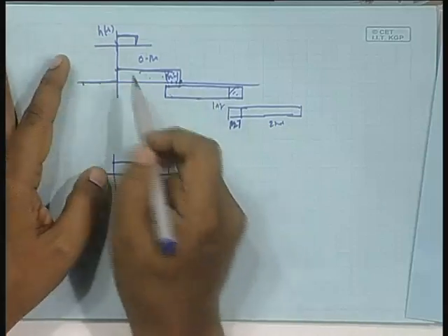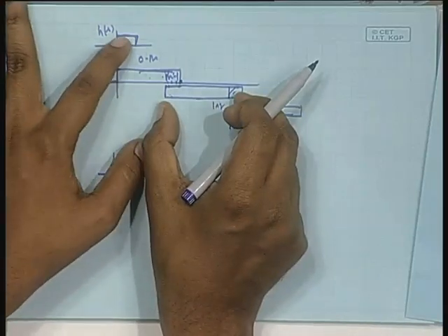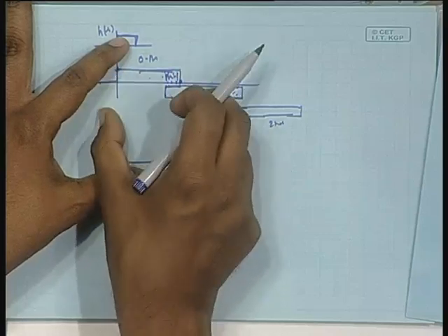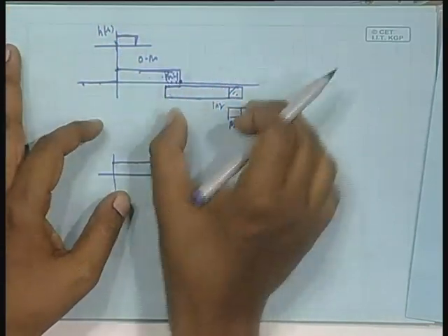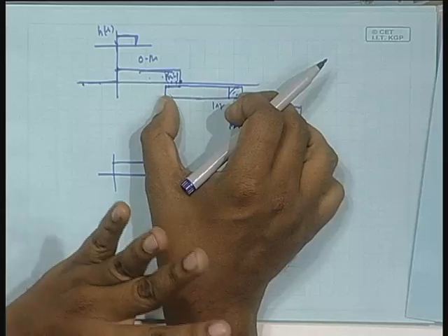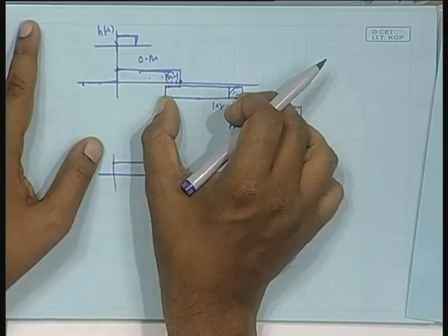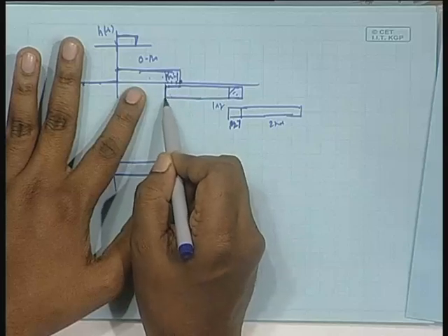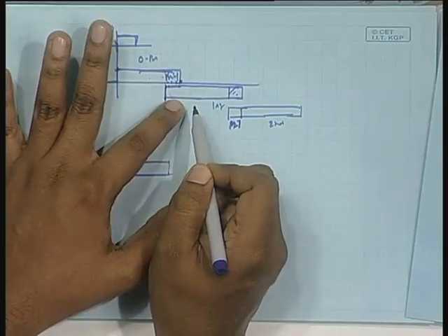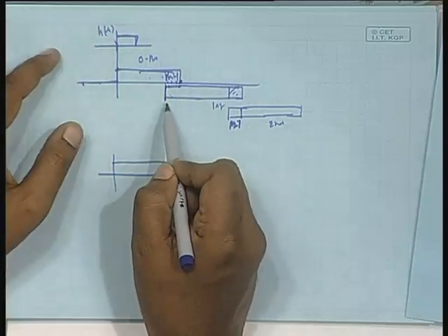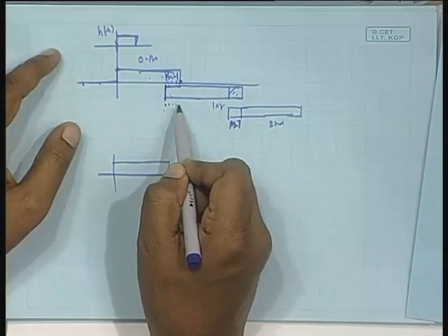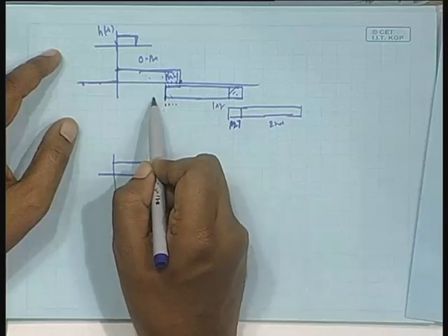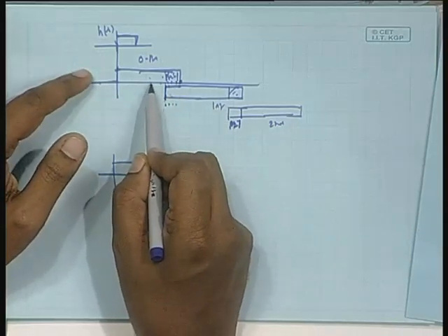Now, you take this block, with this block you want to convolve. Firstly, you can first shift the block alignment, align with the 0 thing, then convolve, whatever result comes, that you place back here. Okay, just for making life simple. So, suppose this is indeed the 0th, I mean this is the vertical axis, this is the origin, you are convolving between the two. That time again at this point, at this point, at this point you get result, but will that be correct result? Answer is no, because to the left of this I have now 0, but originally there was data.